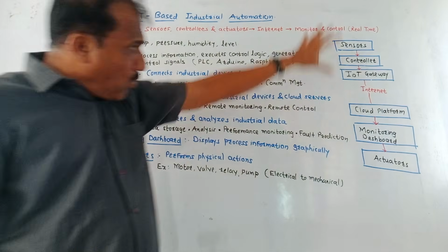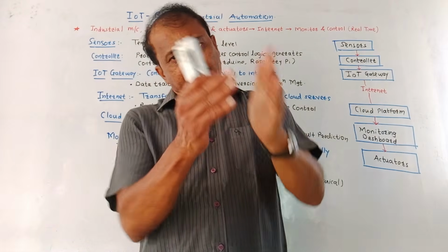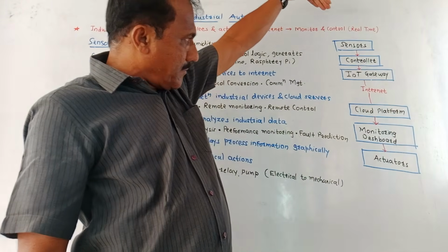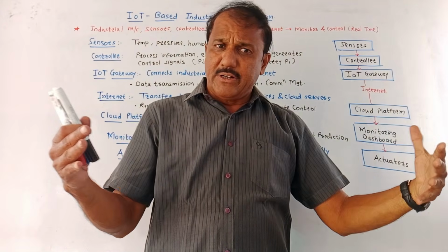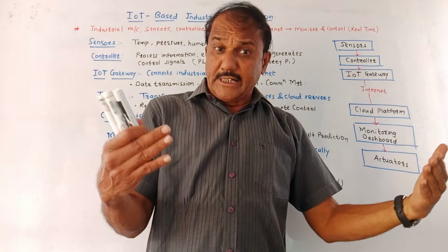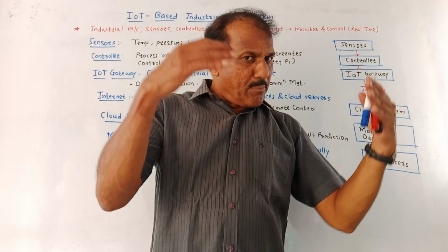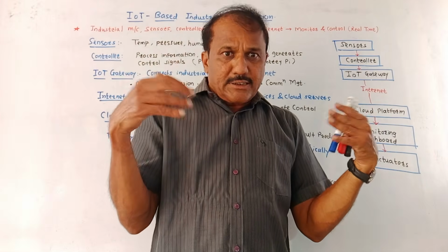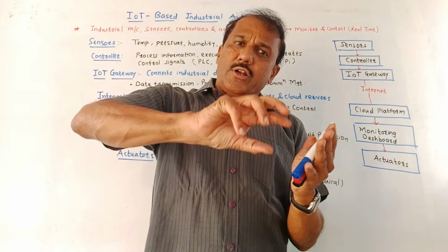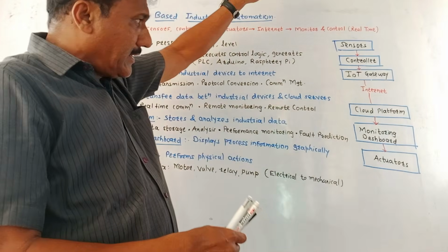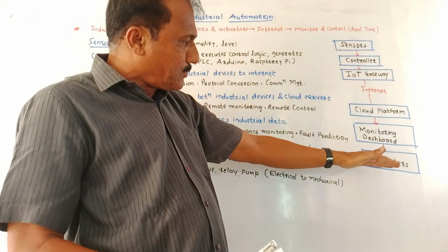Next is the actuator. Now, first we captured the physical signal, converted it into an electrical signal, then the signal is transmitted through all these blocks, and depending on the requirement we generate different signals. For example, in case of the controller, if the temperature of a certain plant starts increasing, then the controller generates a signal and it will switch on the cooling fan. Likewise, there are different operations. So everything is done by making use of these blocks.